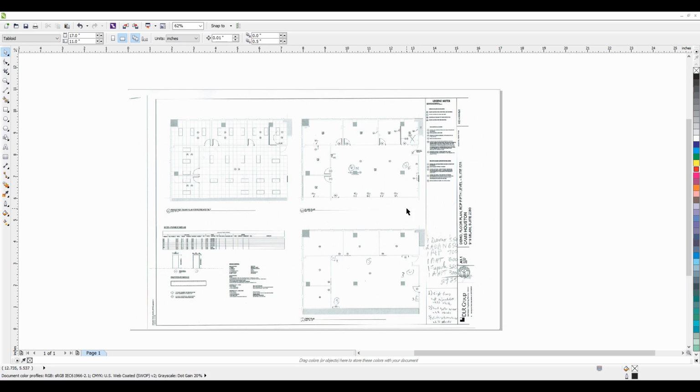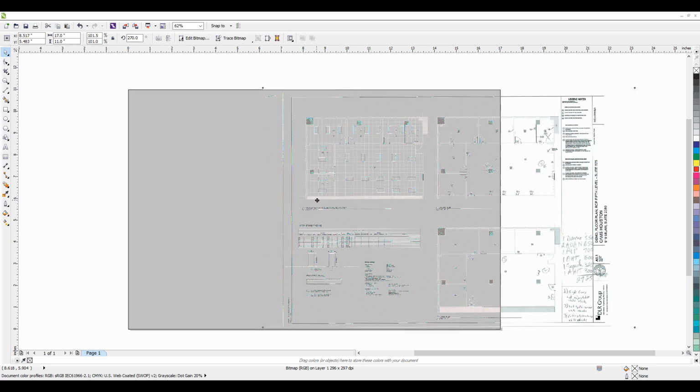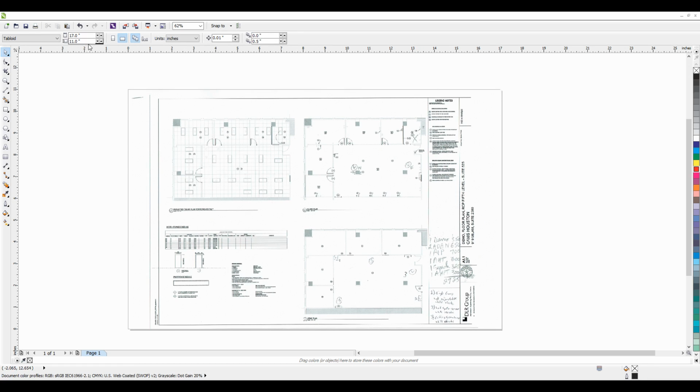If it was going to a printer that was printing 8.5 by 11 in portrait, it would be printing this section. Most of the time, if you're not printing the right size, it's because your printer isn't configured for the right size. You'll have to go in through your driver, change some of the settings, change the paper type, or change the paper size, and you'll be printing out fine, as long as you're set up here to be on the right paper and the drawing's on the right size. Okay, so we've got manipulation down, so we're going to go ahead and continue on to the next video on editing out some of this useless information we don't need.